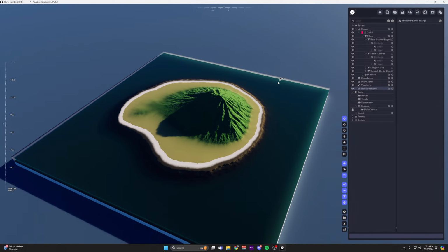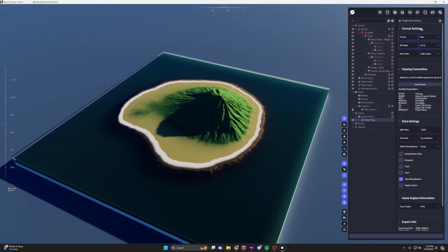Like if you have a survey of an area that you want to come into here, for example, in texture, you can import a height map into Twinmotion. So that's simple enough. You just go to export height map, and we can export this height map. I'll go through the settings and stuff like that.